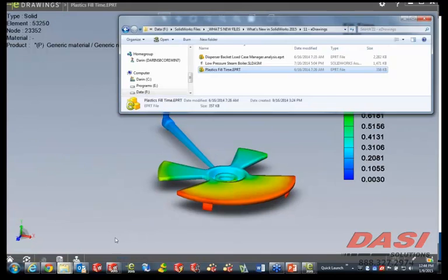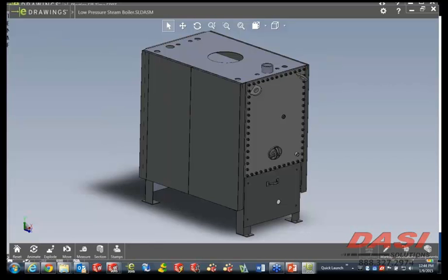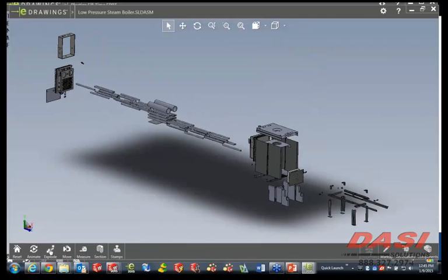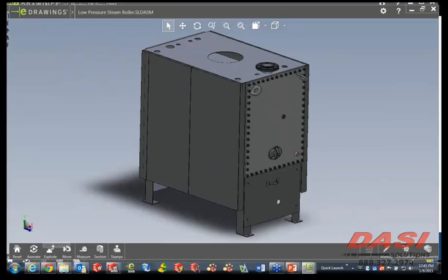When we're opening up assemblies or part files with eDrawings, you're going to get things like your part properties or your file properties. All of these things are now located in the lower right and in the lower left area, so all the buttons that we had there previously. If I wanted to go ahead and explode this, of course, the button's going to be down there for exploding. Animate's going to animate from one view to another if it was a drawing, or from front, left, top, right, and throughout if it's a part or assembly.